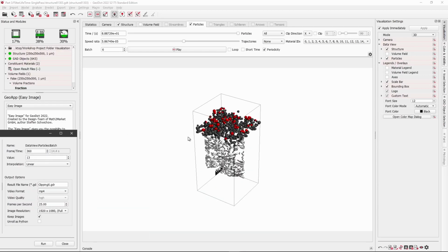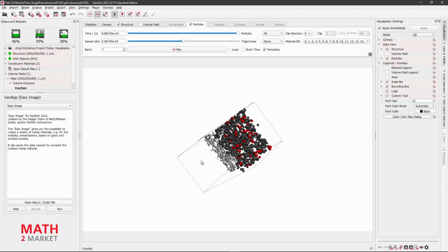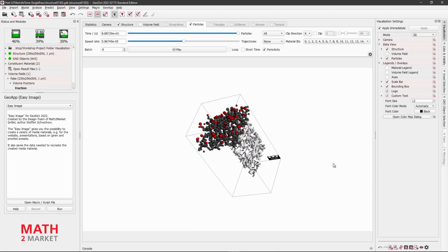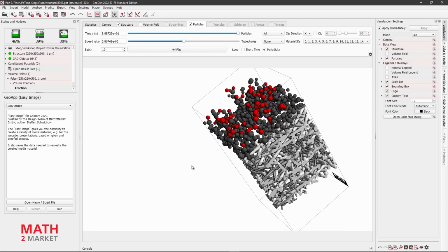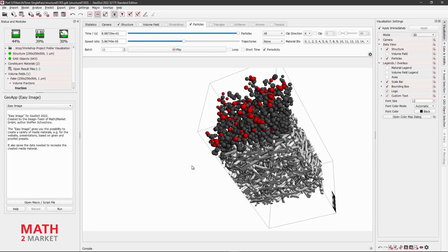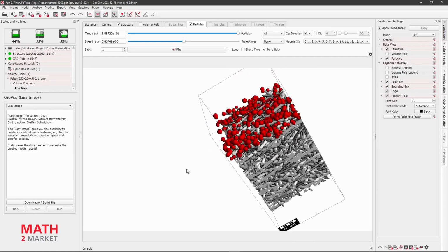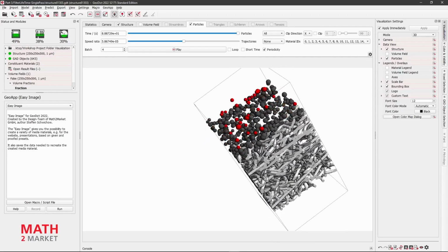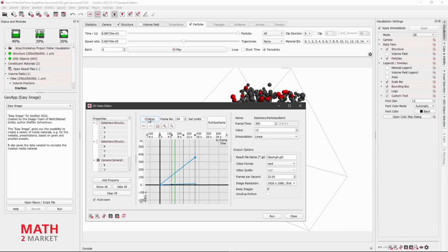If we move and rotate the camera while the animation is playing, the animation continues to play but with a new camera setting. This can be done to quickly adjust the saved video to a new structure, but it makes it difficult to repeat the process again. We would like to define the camera setting so that we can create exactly the same video again. To do this, we stop the playback and maximize the video editor again.